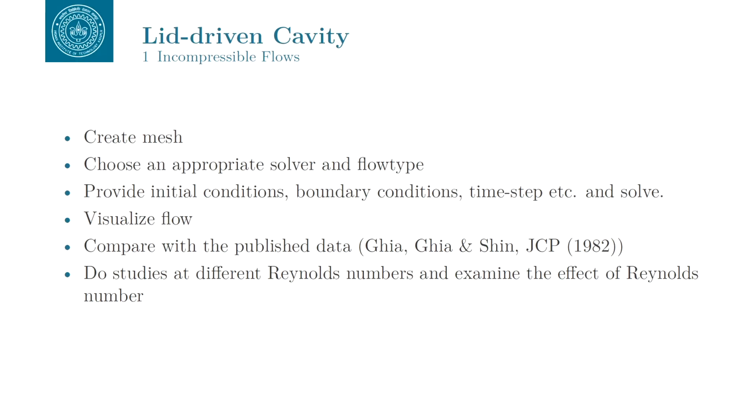If you go to Fluent, for example, you have a pressure based solver and a density based solver, although it is not necessarily a segregation between incompressible and compressible, because the pressure based solver can also be used for compressible flow problems. There you can call the energy equation and solve the compressible flow problems.